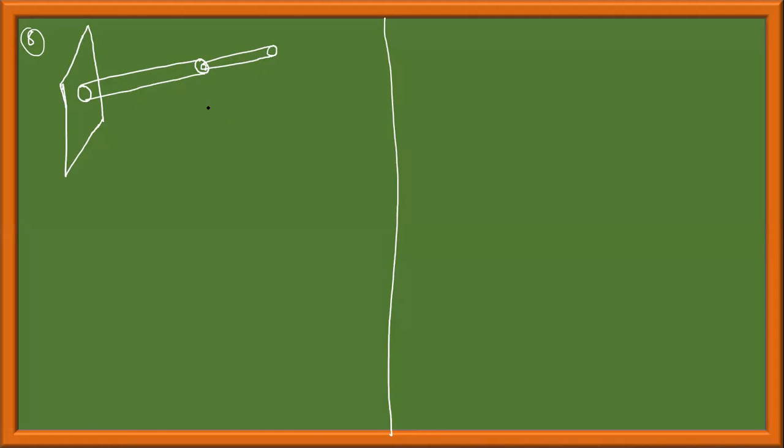This is the shaft. It is subjected at this point to, sorry, this is not 100 kilonewton, this is 10 into 10 power 6 newton mm. Always you should convert into newton mm before solving the problem, because my shear stress, length, everything will be in mm.